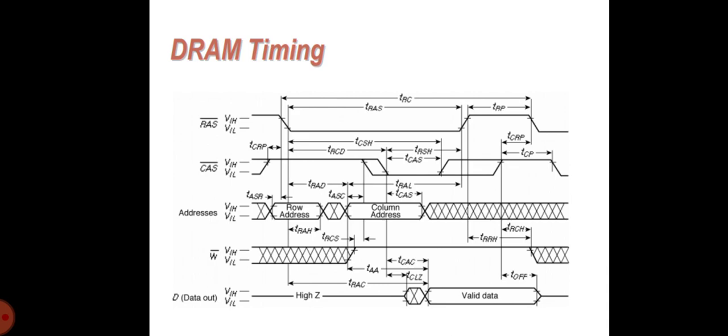It is a common practice to adjust the timing interval with operating parameters by including a model of the word line, that is a dummy word line, in the timing generation circuitry. This delay module tracks the delay of the actual word line accurately, making the memory more robust while preserving the performance. It is thus fair to state that DRAMs combine a synchronous approach at the global level with self-timed techniques for the generation of some of the local signals.